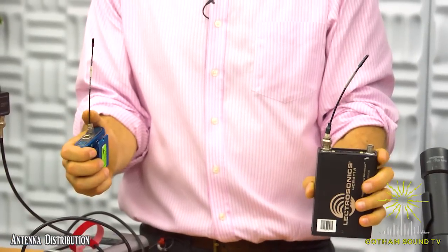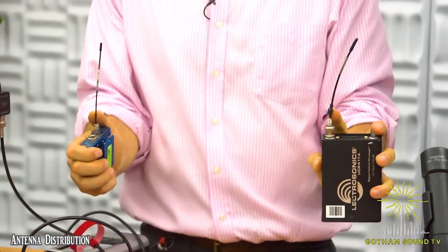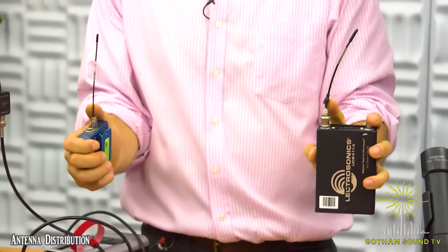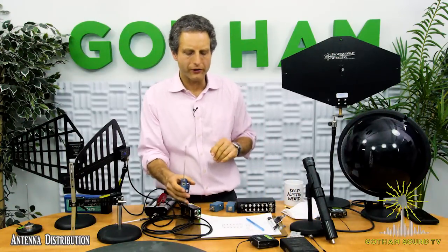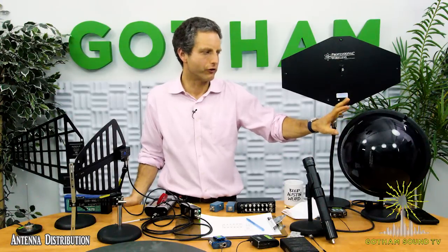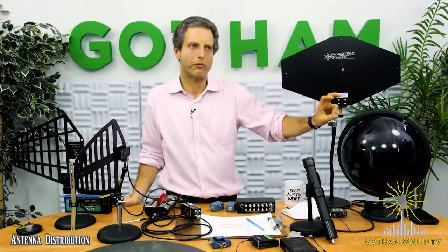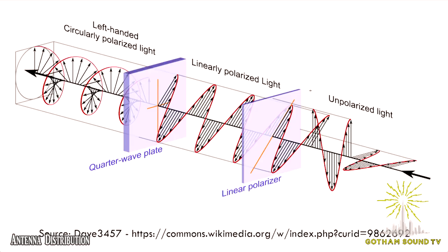So in a perfect world, both antennas would be vertical, and that's sort of the best way to handle that. What happens is RF energy bounces around, and particularly with hard metal surfaces, the polarization starts to change and rotate into all directions. And that's where the circularly polarized antenna, which is sensitive to RF energy with multiple polarizations, comes in handy. I think we have a diagram to kind of show.